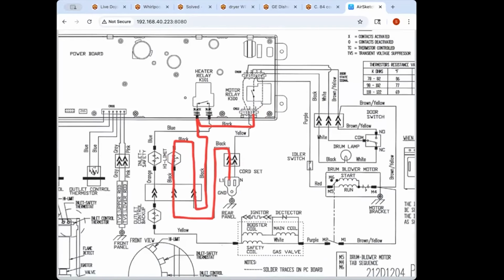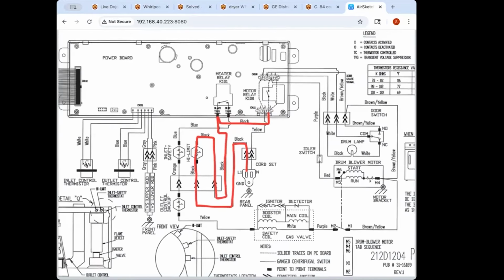So this is why you look at the schematic. You don't try to go from memory. You don't try to wing it. You look at the schematic because it's your strategy planning. It gives you the overall bird's eye view of the battlefield. And it's kind of unusual to see a switch in a board's power supply, but we have that in this case.